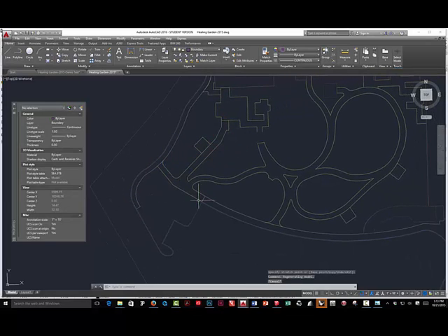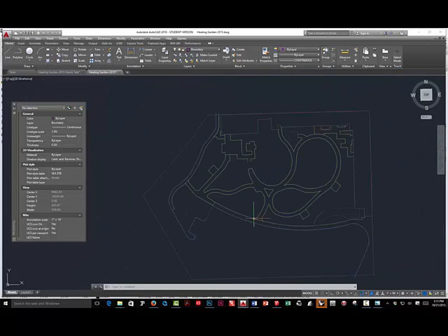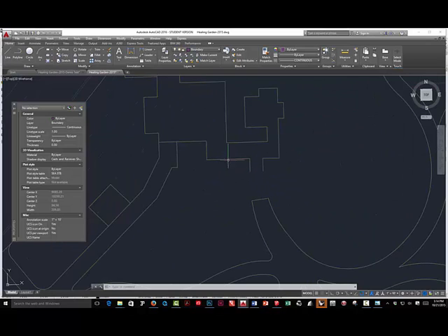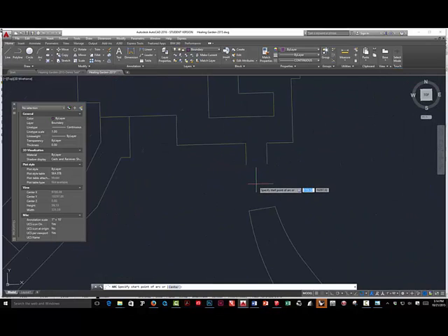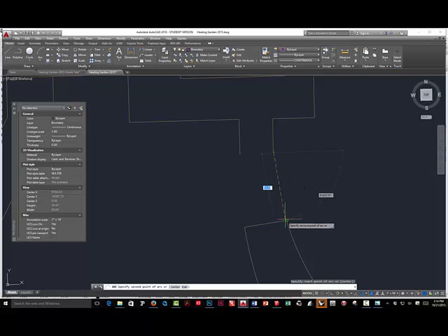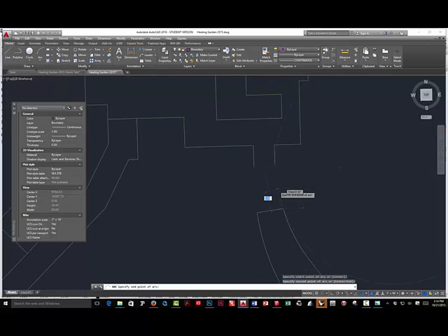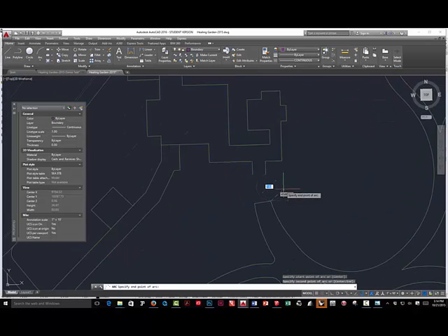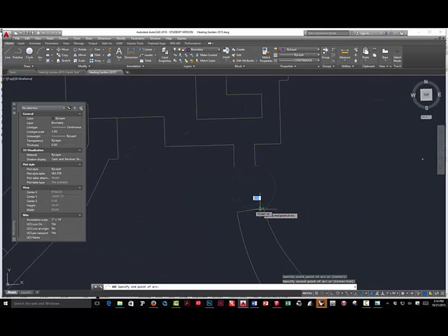I'm just telling you right now, there's a couple errors. One's the bottom of this step. One's up here. I think these are okay down here. And there's a gap here, so I'm going to use my arc tool and just fill that in. That gap is where the stairs are at, so actually probably could use a different arc.